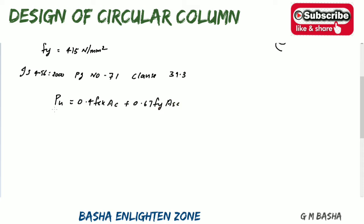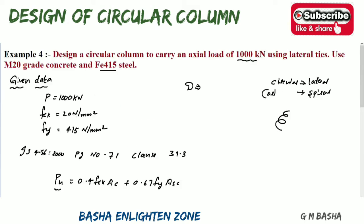The formula is in terms of Pu, which is the factored load, but in the question they have given just the axial load. So in terms of the factored load, Pu will be equal to 1.5 times the given axial load. That is 1.5 into 1000, which is equal to 1500 kilonewtons. In terms of newtons, that is 1500 into 10 to the power of 3 newtons. So that is the factored load value.